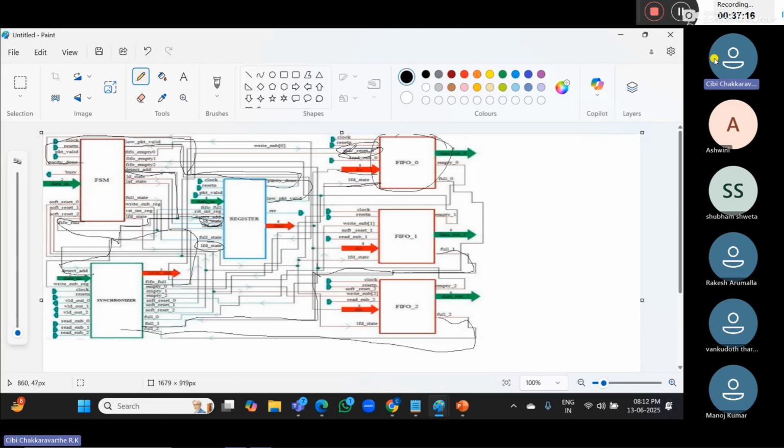Till that 30 cycle, there is no response. Then soft reset will happen. So inside that soft reset, what happens is our signal will go to high impedance state. Instead of getting 0, it will be moved to high impedance state. High impedance state in the sense, our signal will be disconnected.